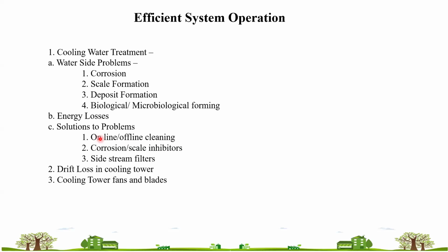Let's say there is a distillation column connected to its primary or secondary condenser, and you are providing high temperature water. Your product recovery is not that much. You are not able to maintain the vacuum in the system, so you are losing out on productivity, and you are losing out on power.